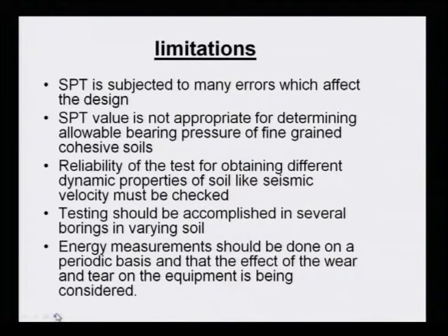Limitations also, as I said: SPT is subjected to many errors which affect the design. SPT value is not appropriate for determining the allowable bearing pressure of fine grained cohesive soil. Limitation 2: the reliability of the test for obtaining different dynamic properties of soil, like seismic velocity, must be checked. How reliable? You should check this data.